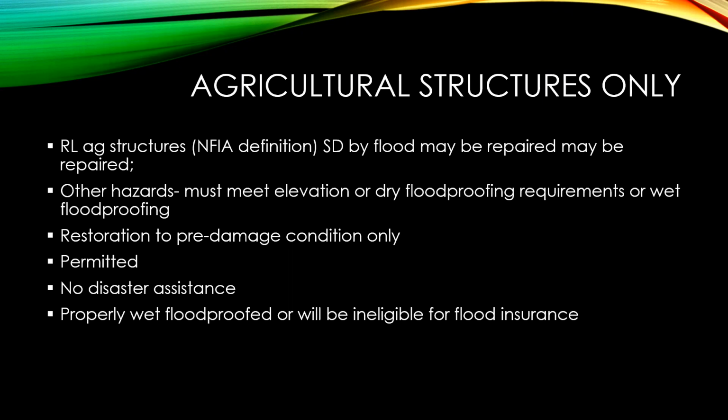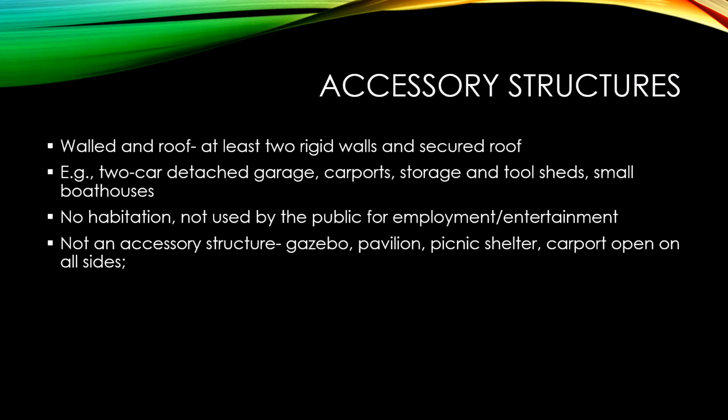Where the public meets is another use that you're not allowed to have. That would also make it a non-agricultural structure. That would make it a non-residential structure, which would then either have to be elevated or dry floodproofed, and you can't wet floodproof those structures.